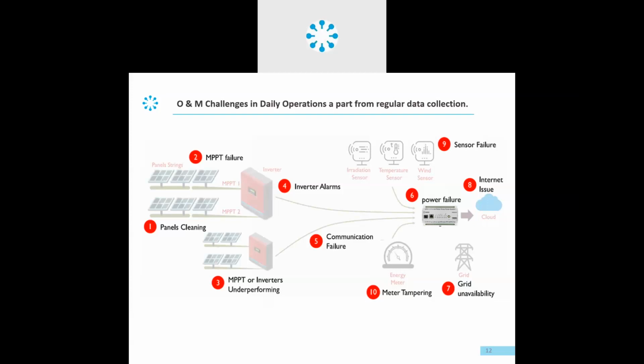mandatory to see, but what we do is we always tend to schedule the cleaning times, every week or every 15 days or every alternate day, depending on the location where we have installed our solar, and the importance of that solar. Again, it comes up with the capacities normally. But we do not tend to go by capacities. We always treat even the lowest capacity of solar as of utmost importance, as we used to see at megawatt levels. So panel cleaning is of foremost importance, because this is the one which you only feel when you see that your production is falling, but you don't have any clear reason why.